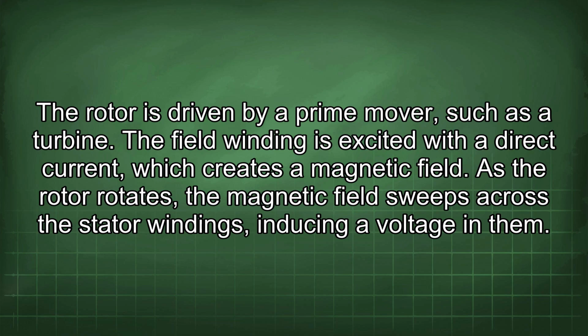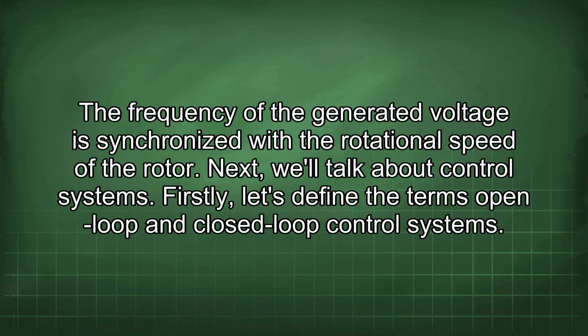The field winding is excited with a direct current, which creates a magnetic field. As the rotor rotates, the magnetic field sweeps across the stator windings, inducing a voltage in them. The frequency of the generated voltage is synchronized with the rotational speed of the rotor.